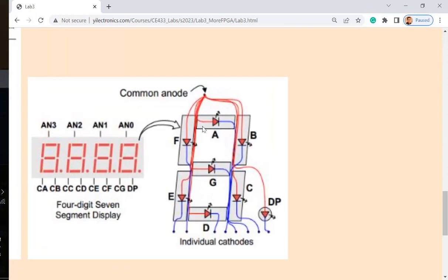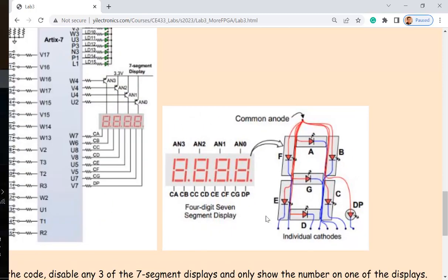So you know the LED bars for the display are A, B, C, D, E, F, G, and P. These are the digital lines turning on and off these LEDs, and they have a resistor. Is that called a pull-up resistor, or a current limiting resistor? Current limiting resistor. Okay, you don't need to pull up anything. And you have 4 more bits here. You can see only 7 bits, right? Only 8 bits including the point. You got 8.